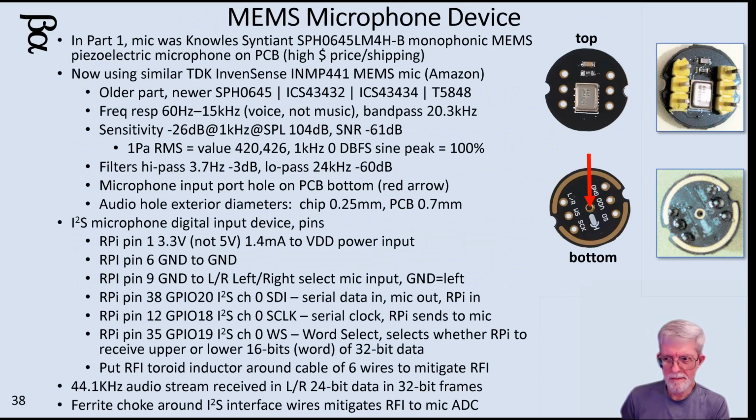Here's more details about the microphone device. You can see the pictures on the rightmost ones. Those are actually what I did. So I soldered some pin connectors onto the top side of the microphone, making the bottom side open for me to be able to shine light into it, LED light. And there's that, and pins and wiring and signal numbers.